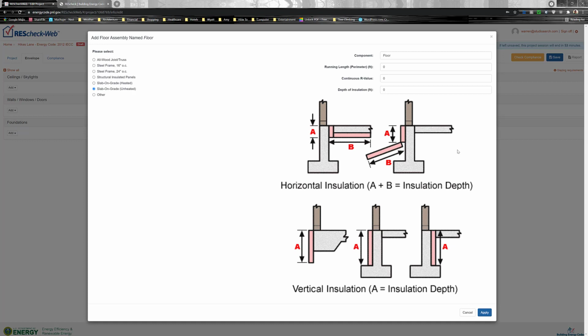That's when your delta T on your ground is the biggest, right? That's why we have frost depth. The deeper you get, the less delta T, the less temperature differential you'll have, the less efficacy you'll get out of your insulation. So for me, I'd say I usually do an R value of 10. That's a 2-inch foam board, and I usually put it down 2 feet.